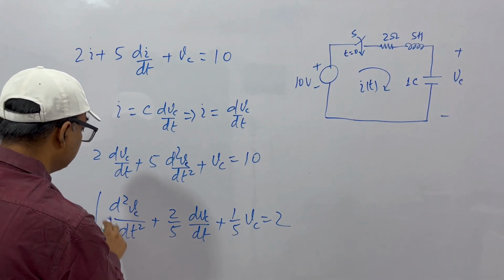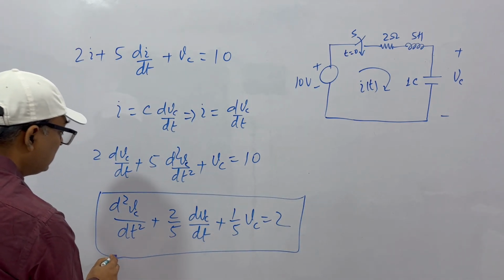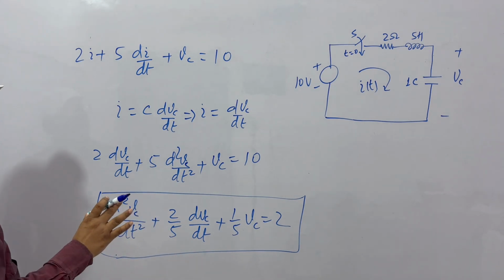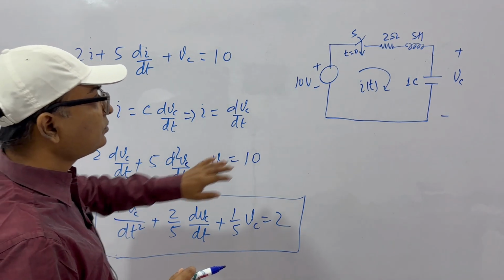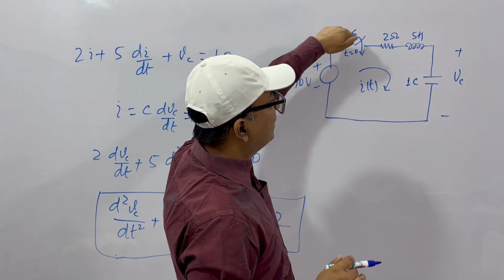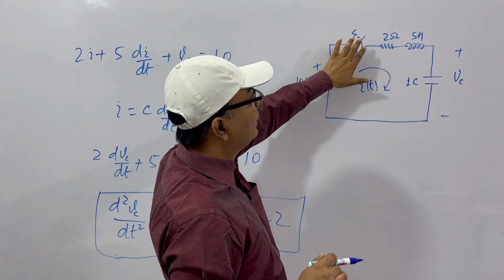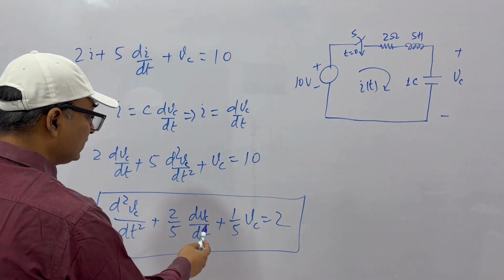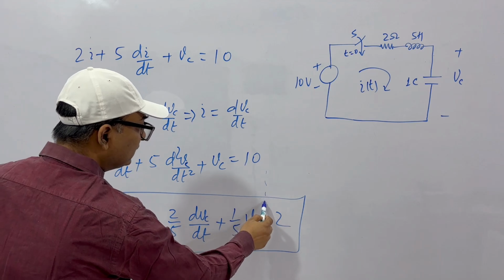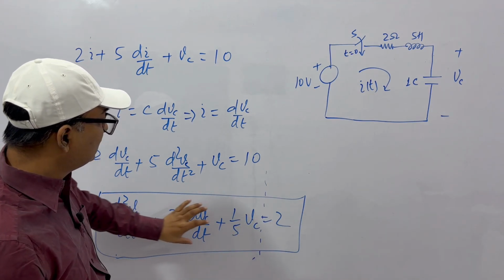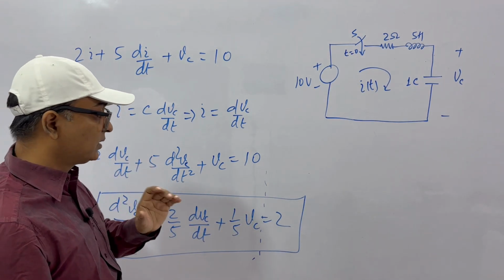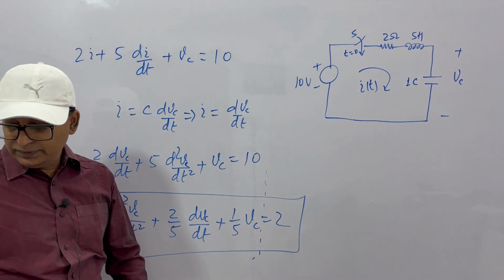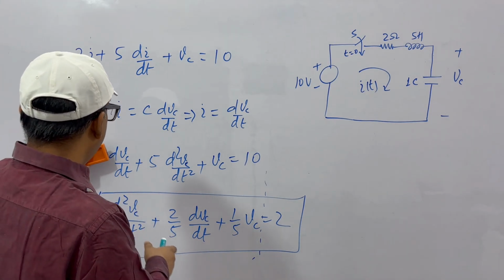So this is our equation. This we have done using RLC when we were analyzing the circuit. Now from here what you should understand is, we have done the simple RLC in a circuit. That was a natural response, and here we have a voltage source, that is a forced response. Now from this equation you can see that there are two parts. First, when this is equal to 0, it gives the natural response, and this part gives the forced response.